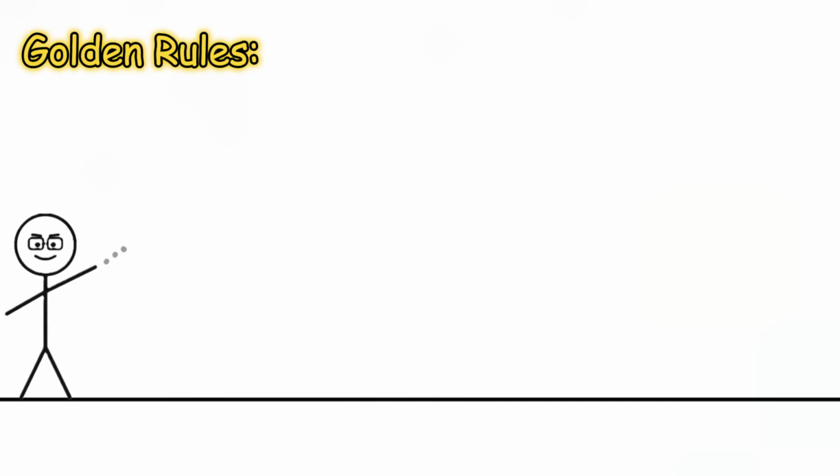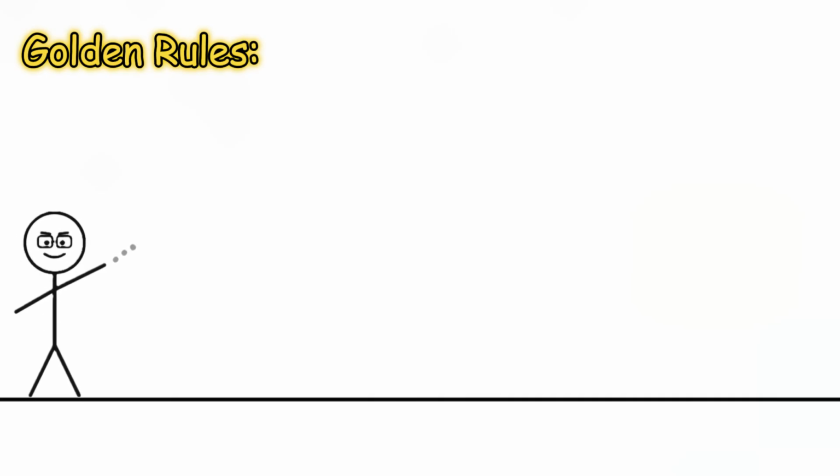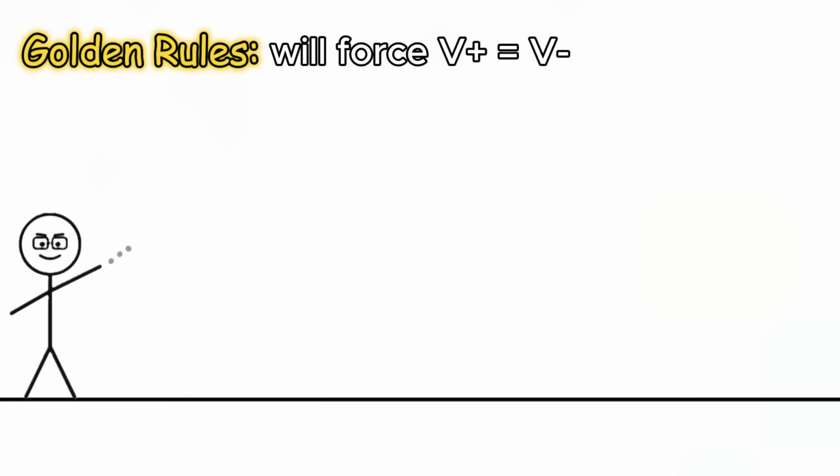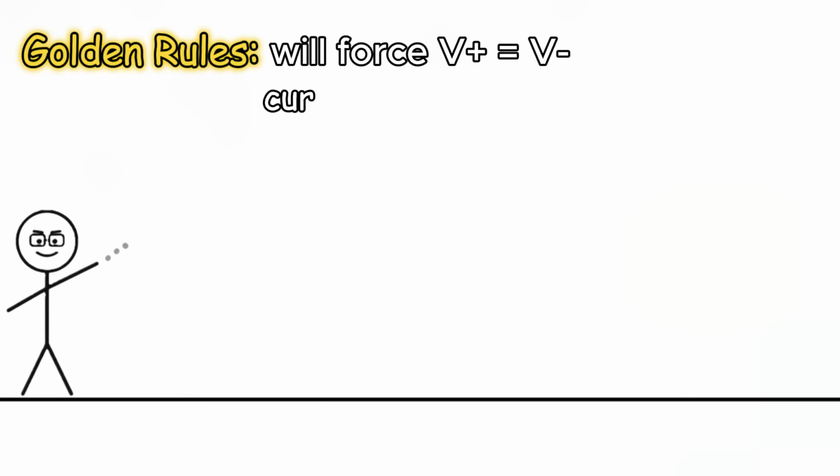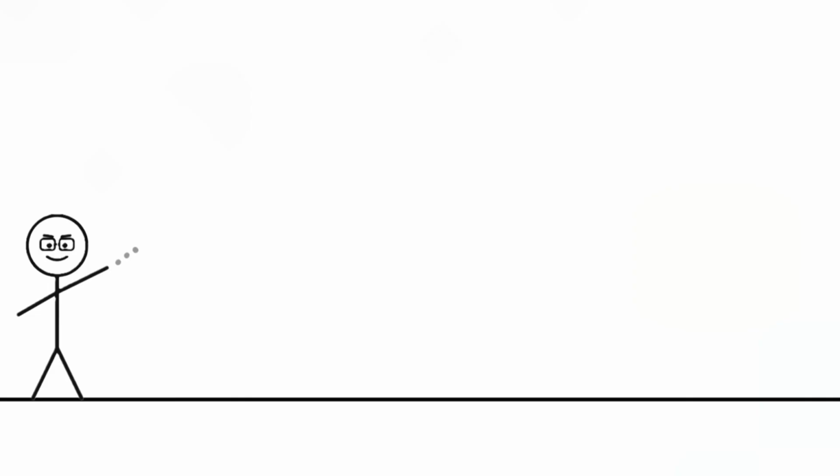The op-amp will do whatever is necessary to make the voltages at its two input terminals equal, while drawing effectively zero current into those inputs. This forced stability allows the op-amp to perform essential tasks ranging from summing multiple audio signals and filtering out electrical noise to acting as a voltage follower or buffer, which gives a weak, fragile sensor signal the electrical muscle to drive a heavy load without losing a single millivolt of accuracy.